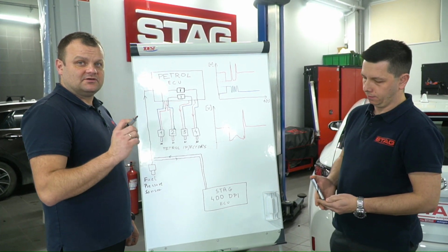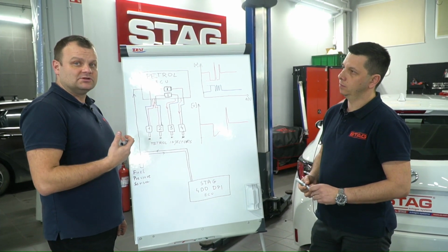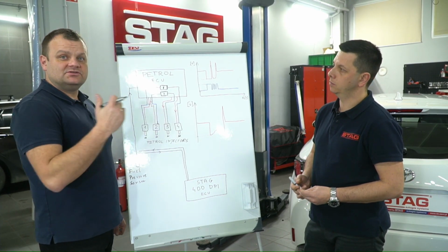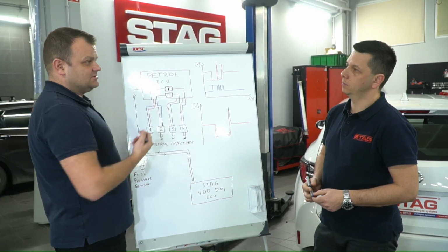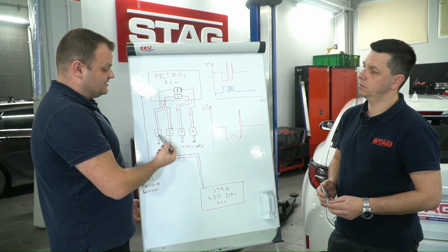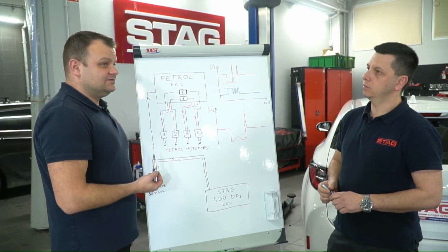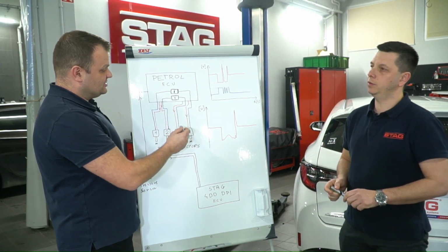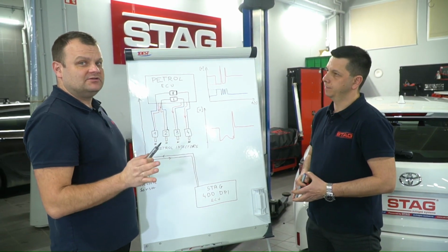It's included in the AC Stag application that you can download from the website, of course. So if the engine is not on the official list, you can follow these rules. It means that you can easily work out which injector is second, third, and fourth. And then, of course, you can use a simple multimeter to check which injectors are paired. Just to simplify it. Also, you can find it in the manual.